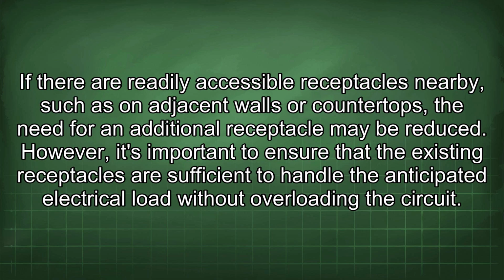When evaluating the necessity of a receptacle on a narrow countertop, consider the proximity of other receptacles in the vicinity. If there are readily accessible receptacles nearby, such as on adjacent walls or countertops, the need for an additional receptacle may be reduced. However, it's important to ensure that the existing receptacles are sufficient to handle the anticipated electrical load without overloading the circuit.